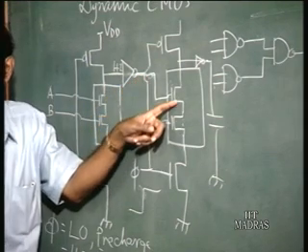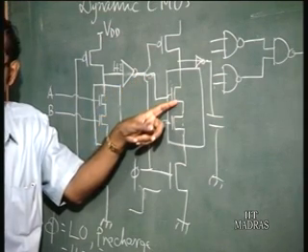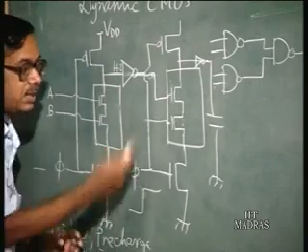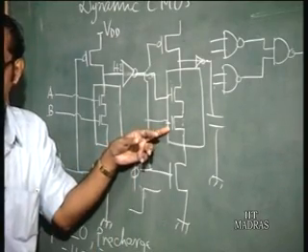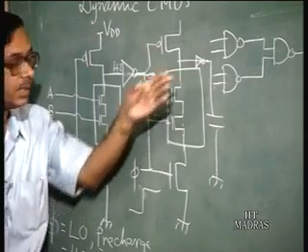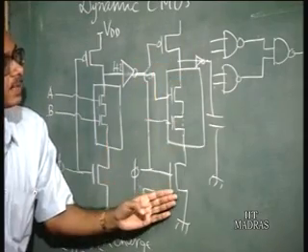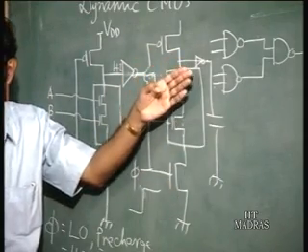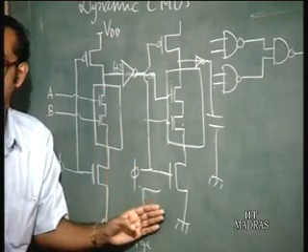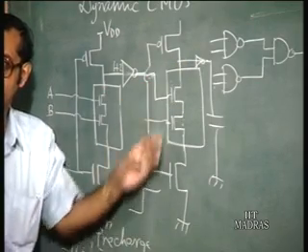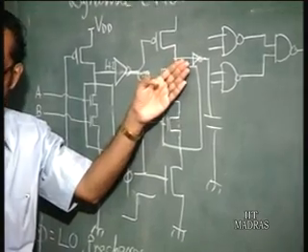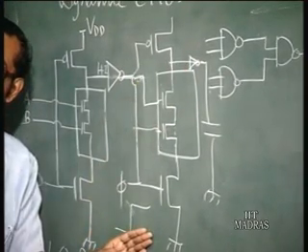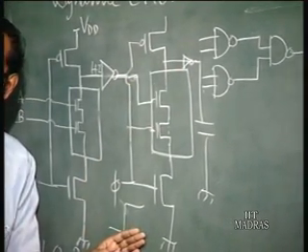So then only this transistor turns on. And suppose this input is coming from a similar gate, then only it has a chance to turn on, and once it turns on, then only this capacitance, the input of this inverter, can get discharged. So the capacitance of the inverter was charged to VDD during the pre-charge phase, then only it gets a chance to discharge.